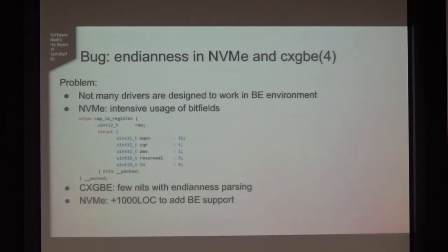So fixing the NVMe required us to go back to the generic stuff and the typical approach to access registers. I mean, using masks, using offsets, logical shifting, and endianness conversion. Of course, the code now looks a lot worse than the code using bit fields, and it's not something very proud of, but actually it works.